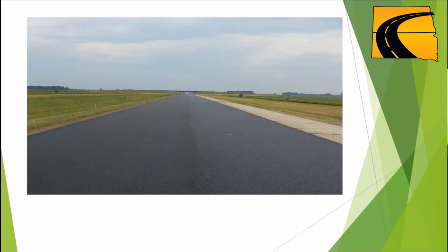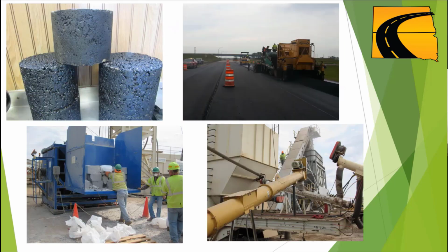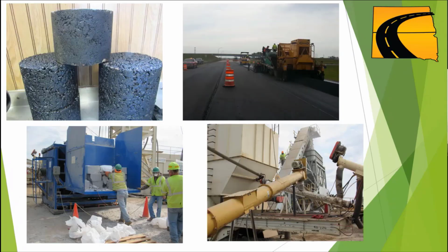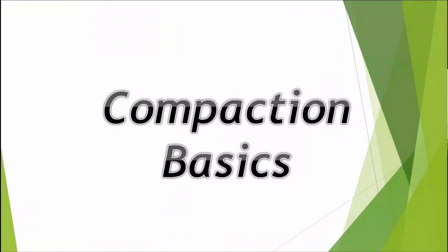Generally, when you start seeing fat spots, you need to check your fiber load and make sure you're controlling the drain down, or run a drain down test, so you don't end up with these puddles of asphalt. The lower left is cellulose fiber, basically chewed up and baled newsprint. The lower right is the fiber feed, which is generally done on the baghouse fines return, with a clear line so you can make sure the fiber's feeding and chewed up.